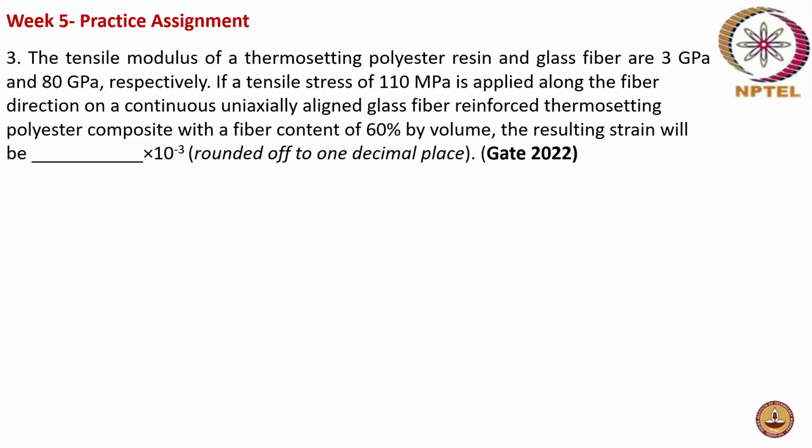Any thoughts? Let me give one more clue. You have Hooke's law, right? Stress is proportional to strain, so stress is equal to modulus into strain. Now which modulus do you have to take, and how do you take it? Maybe 3 into 0.4 plus 80 into 0.6.